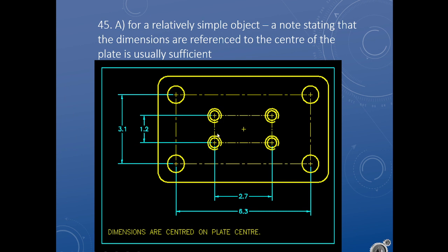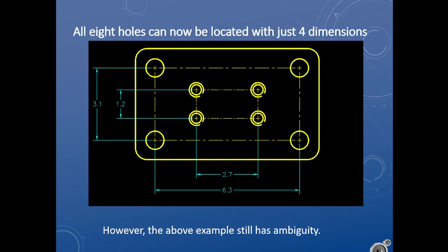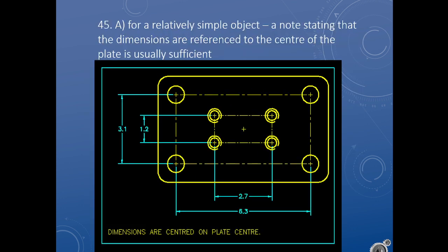Yes, the outer circle is our major diameter on threaded holes. It should be, but it typically isn't. In SolidWorks it'll do it for you, but often the inner hole is just done by eye. It's just so it's visible.